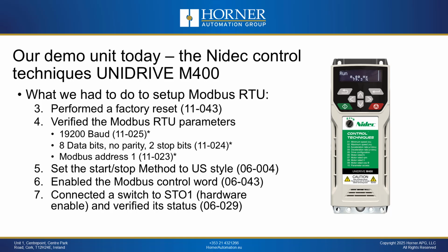Now, in terms of the serial parameters, we did not change any of them, but we did go in and have a look at them in menu 11, and you can see the baud rate, data bits, along with the Modbus address are all available in menu 11.